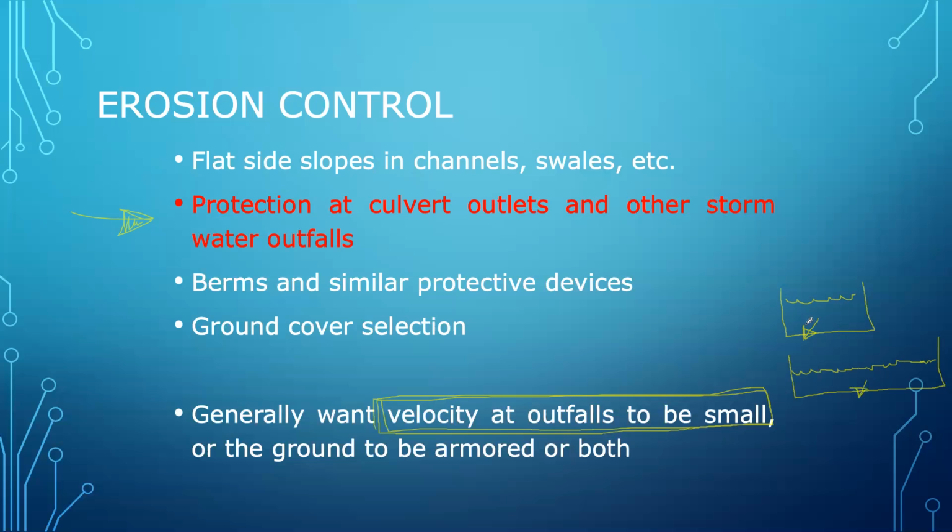See, make the velocity lower there. I'll make this one longer to represent a bigger velocity. So that's really what our goal is doing, is we want to control the length of that yellow arrow, which is our velocity arrow. And the main tool we have is to deal with a discharge area and or the total energy contained in the water. Because the other thing we probably don't want is for that to be supercritical.